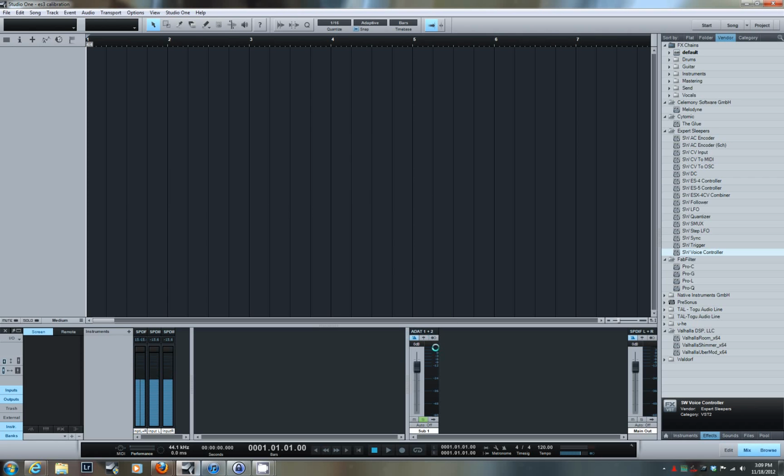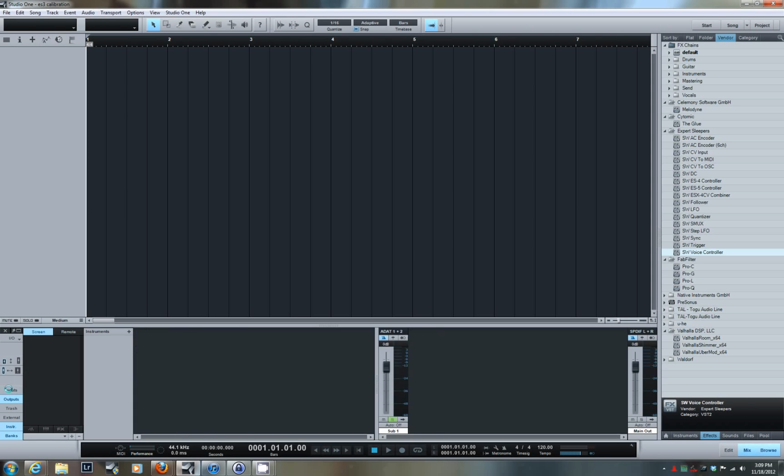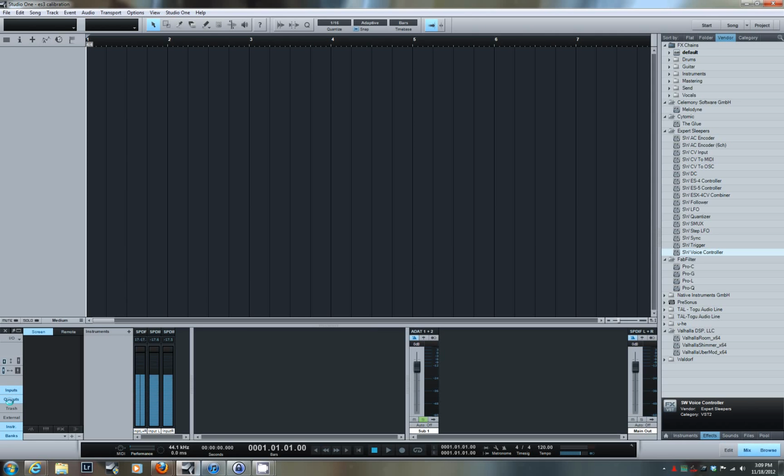And you can see that output channel, the first 2 channels of my ADAT port, appear in the mixer console. If you can't see the mixer console, click on the mix console button in the lower right hand corner. You can also make sure that you're displaying both the inputs and the outputs. Sometimes I don't have all these things enabled, but for demonstration purposes I wanted you to be able to see the actual outputs that I was creating. Okay, so we have this stereo output. It's mapped to channel 1 and 2 on my ADAT interface connected to the ES3 module.